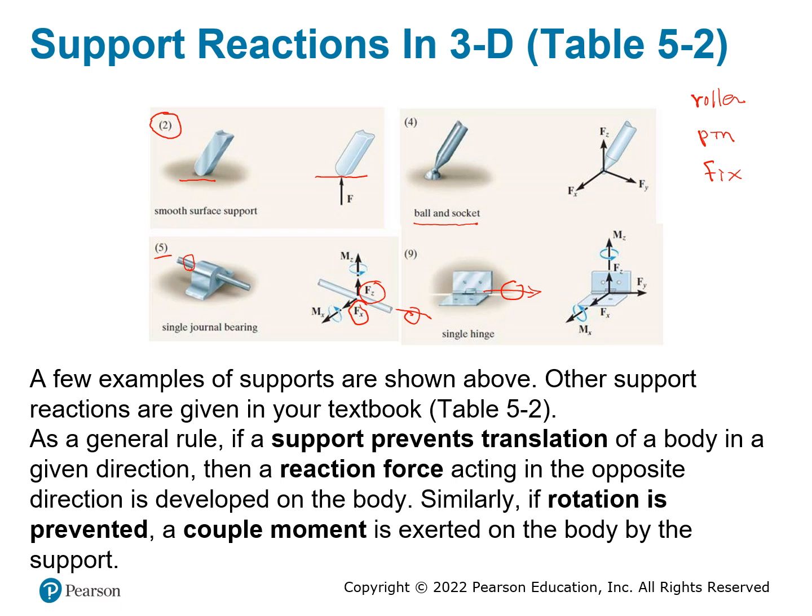Then this hinge is prevented from freely moving because you have a nail here and a nail here. Since it cannot freely move, you are going to have a reaction force, which is Fxy. So here, there are 3 different forces to prevent this hinge from moving around, right? You do not expect it to move around.